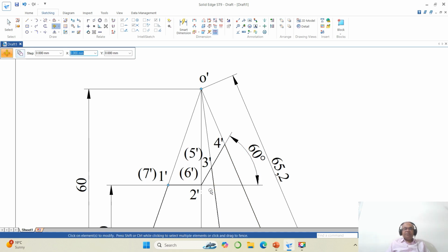Now the sectional plane is passing through this, so we need to consider a line from end of this to take this till here and go to trim. Okay, you got this till here. Then you have one more, that is from here to here, because this is not in true length. So I make it to find the true length of this, but this is already in true length, so you are going to get that point directly here.